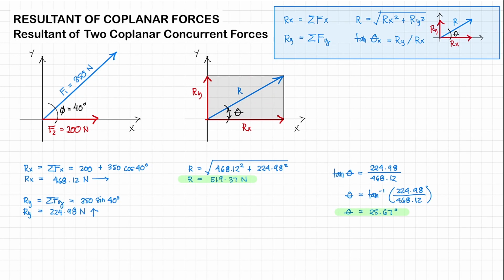Although we have shortcut methods or calculator techniques in solving for the resultant, it's important to know the fundamental solution for this kind of problem using the analytic method. Because, for example, what if we don't know one of the forces, F1 or F2, but the resultant was given, and we are going to solve for the unknown force? We can't use our calculator techniques to solve for that one. So we need to use this analytical method or our fundamental solution in solving for our resultant forces.